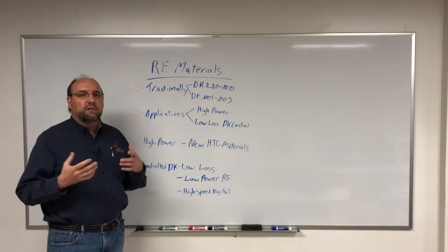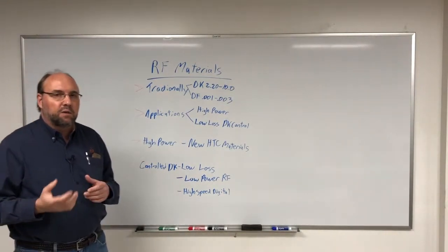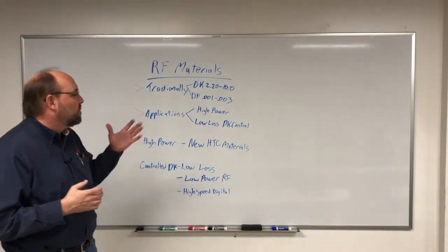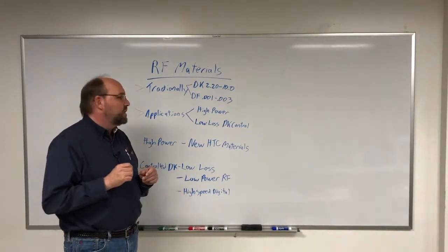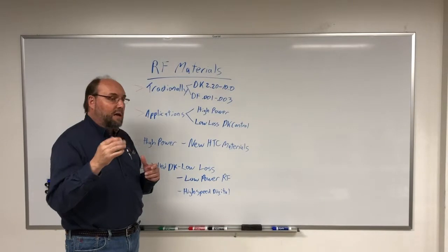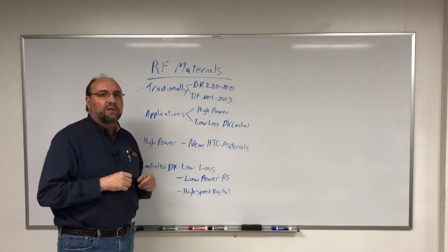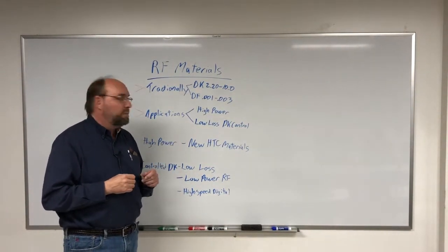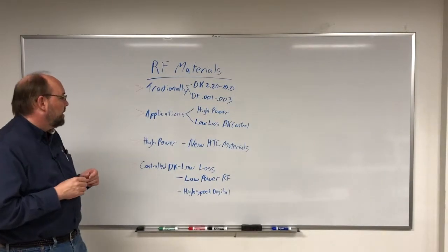But there's materials that don't require high heat dissipation or power handling capabilities, and those are more concerned with the loss of the material, its ability to be able to send a signal through or across that material, and its tight dielectric control, so we have very tight impedance across that circuit.